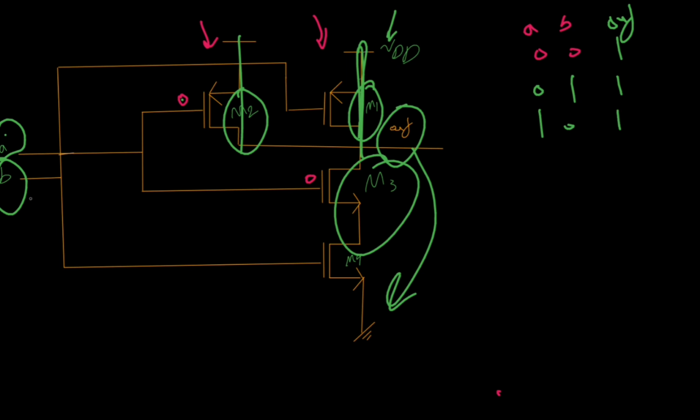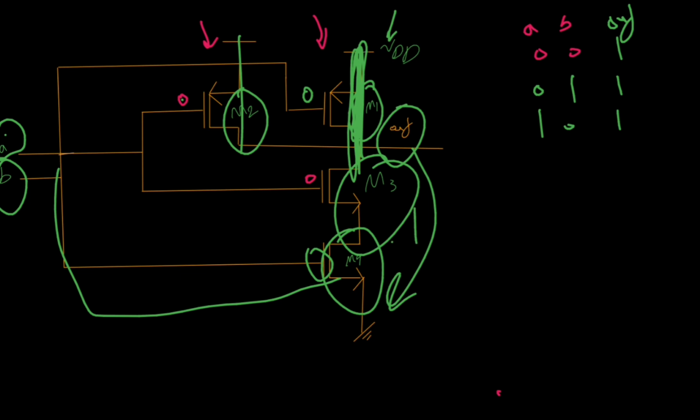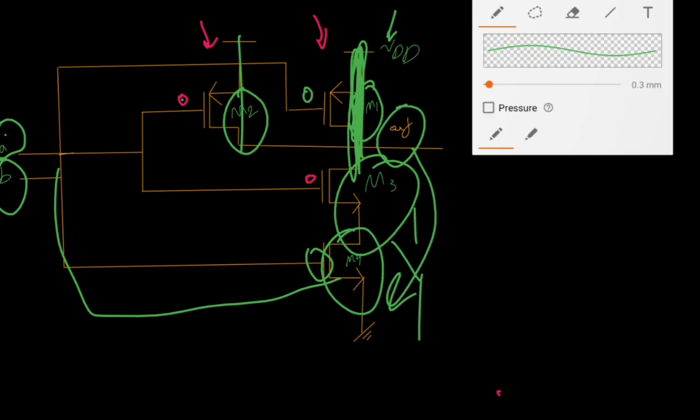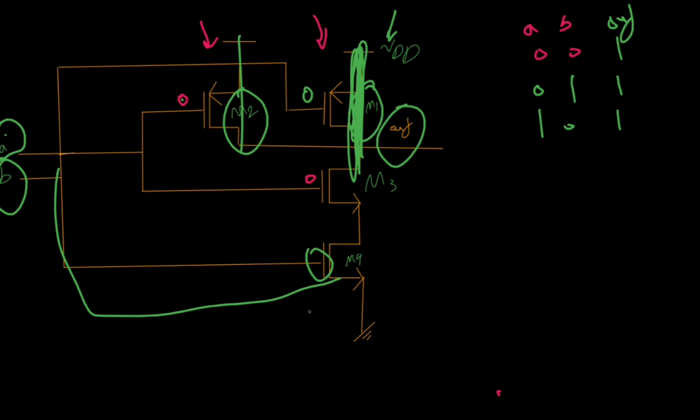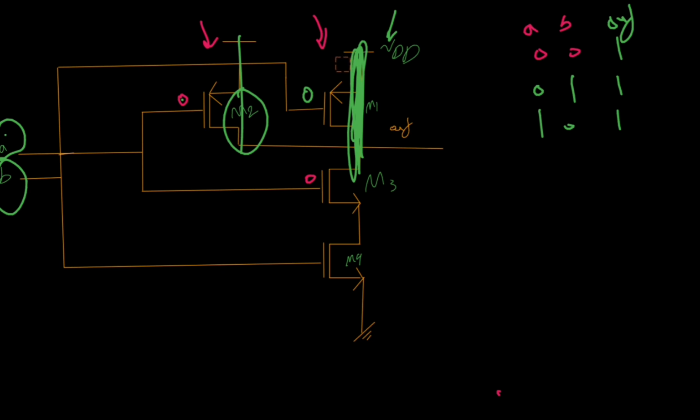Give B as an example 0, only that 0. And you would see that it would cause this PMOS to be connected directly to the out. And obviously it is connected to the M4 gate, which would be off, and therefore it would have an open circuit here. The only time that out is connected to the ground is when both of the inputs are equal to 1. Let me just wipe some of these things out. Too much. So let's just say that this time we would have both equal to 1. Also, let me change my color so you could better see what we are doing.